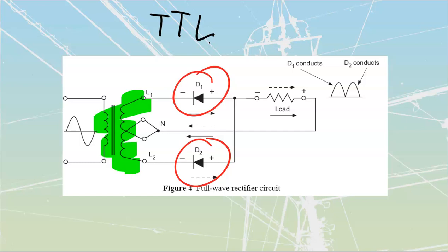If we're looking for DC power, it's going to be like 24 volts in a lot of cases, which we're going to be utilizing for contactors, small motors and things like that. So it depends on what your application is, but in most cases you will be dropping from line voltage, VL, down to TTL values or down to 24 volts. So in a lot of cases you need to have something that can drop that value anyway.